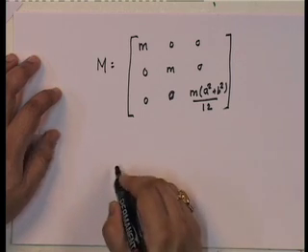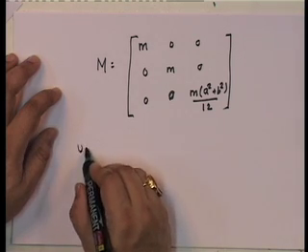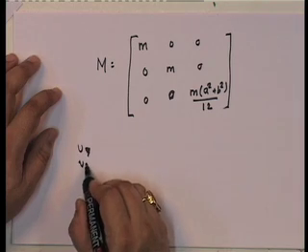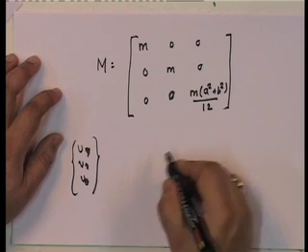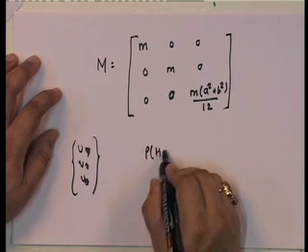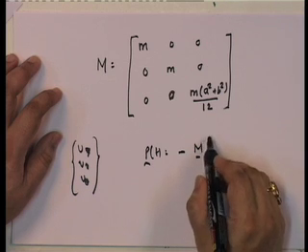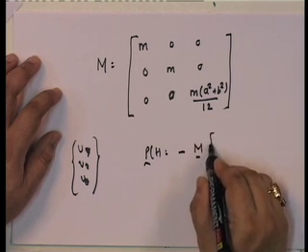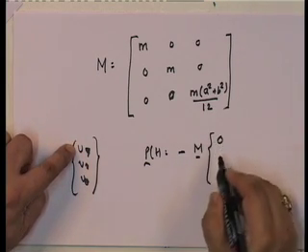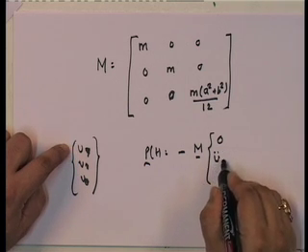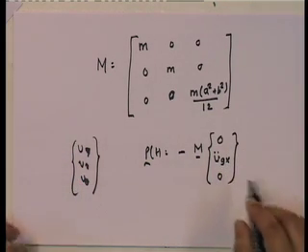So now on the opposite side, I have u, corresponding to vy, vx, and v theta. Now if you are looking at the loading vector P, this is going to be equal to minus m into the M matrix multiplied by the ground acceleration. What is the displacement in this case? This is 0, this is v double dot gx, and corresponding to this is 0. So this is what the P looks like.